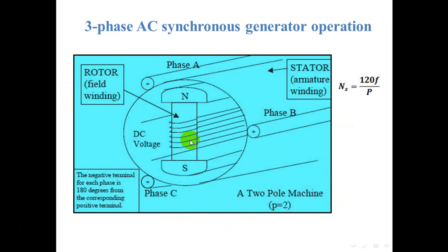Now, if we consider a practical synchronous generator, then field magnets rotate between the stationary armature conductors. The synchronous generator's rotor and shaft or turbine blades are mechanically coupled to each other and rotate at synchronous speed. Thus, the magnetic flux cutting produces an induced EMF, which causes current flow in the armature conductors.